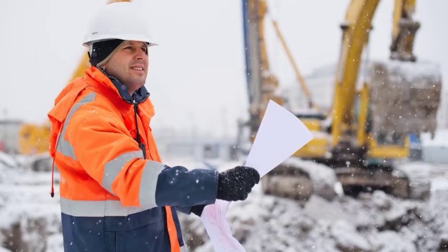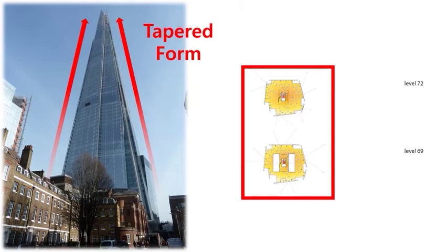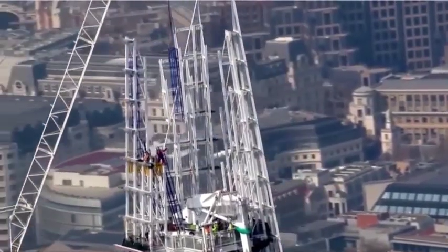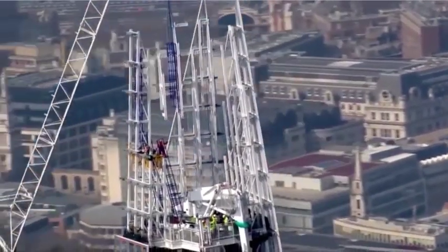First, construction progress at the winter period. Cold weather and short daytime disrupt the construction. Second, small space at the spiral level due to tapered form of the shaft. Small space can allow only a few workers and materials, which limits the speed of construction. Last, the wind blow. This affected the crane movement, which was used to assemble the module.